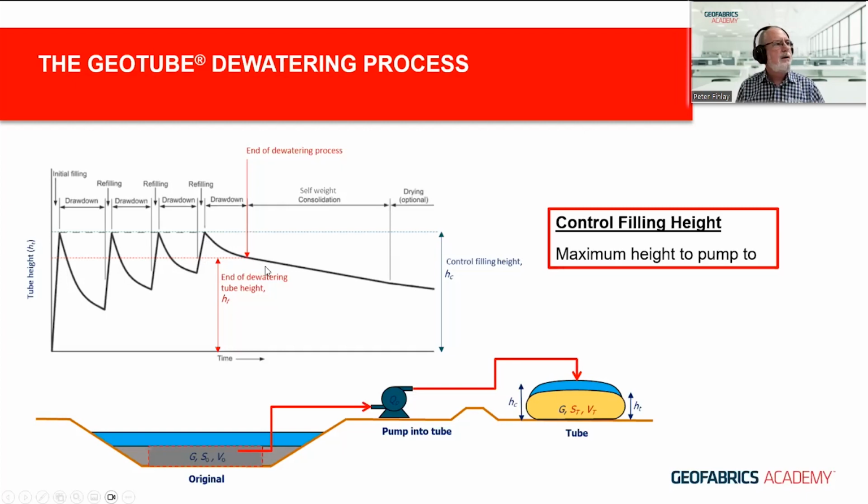And this is the time will be dependent on climate and the sludge, and it's not an overnight thing, especially for organic wastes. It can mean several months on site before it reaches that sort of, say, 25% where it can be excavated and taken to waste.